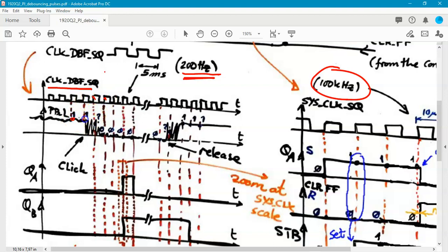So you are sampling once and then something obscure or not defined, and then you are sampling zeros. And for example, in this way that we've done in the debouncing filter example, after detecting three consecutive zeros, we are going to have a very perfect digital pulse that is going to last for 5 milliseconds.